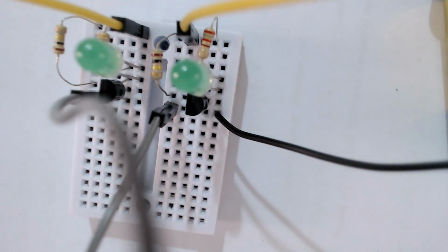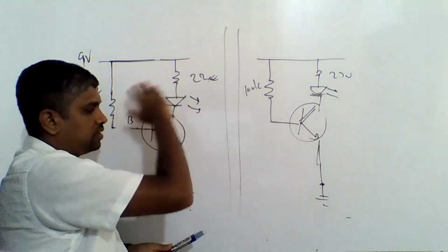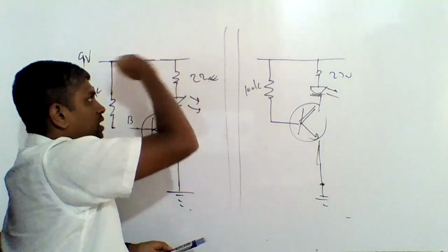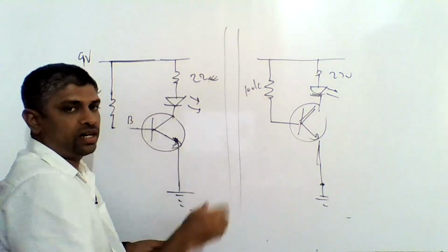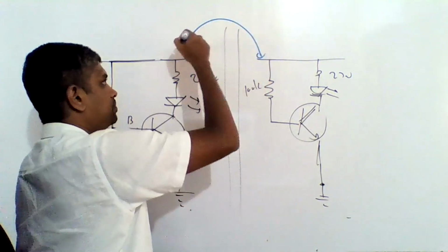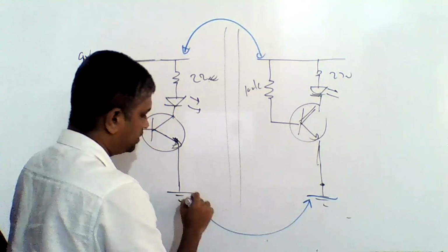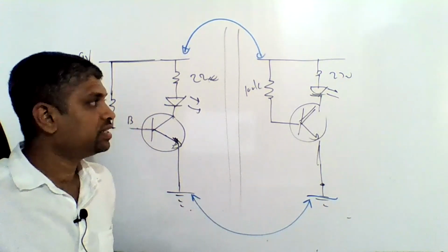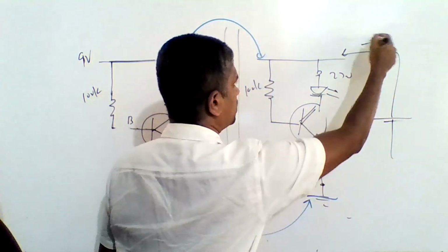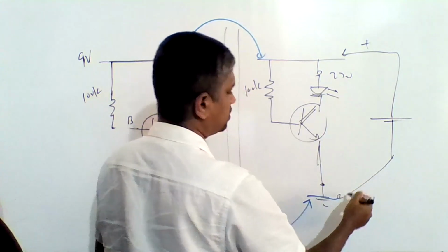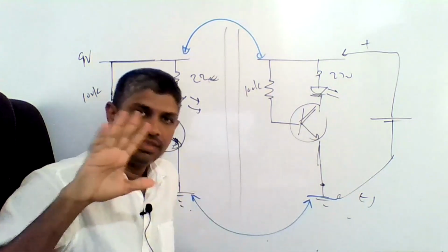Look, you have to do it like this, because you have used either side of the breadboard. You know the first row has 5 pins, again there's the separator and another 5 pins, so these two are not connected together. You can use a jumper to connect these two together. Then with one supply, your supply may be here, a 9-volt battery, we only provide positive and negative connection to one side. They are connected, therefore both the LEDs will light with the same brightness, right?